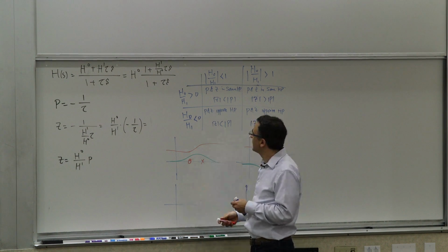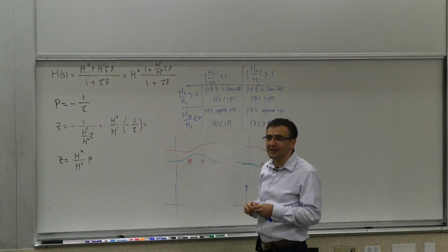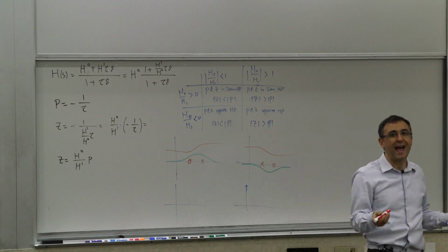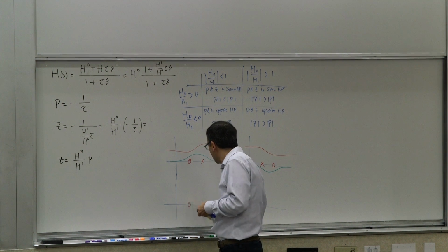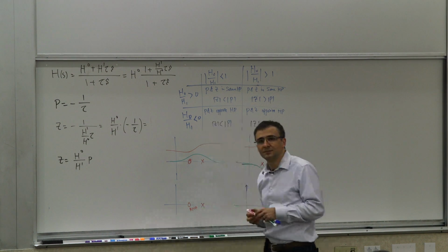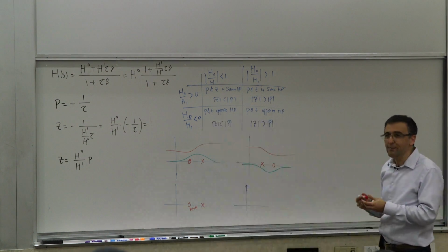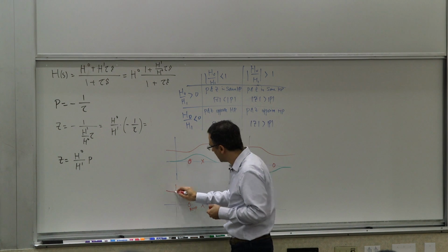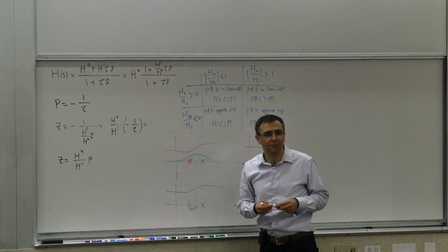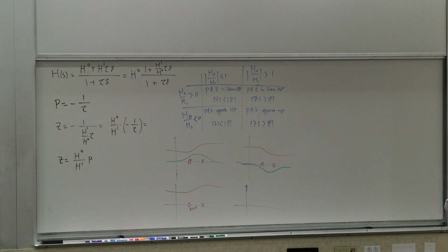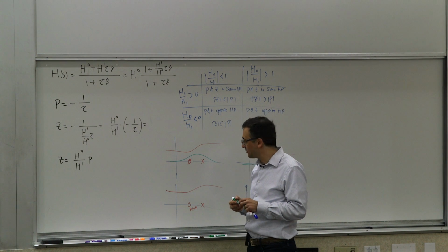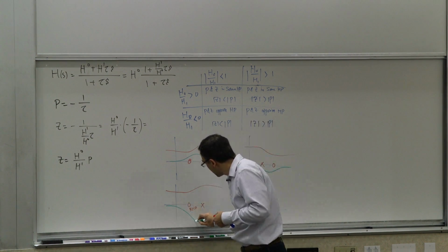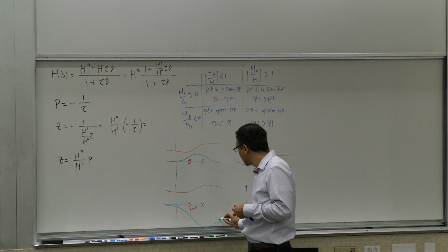Now, how about this case? When they are in the opposite half plane, let's say you have a left half plane pole and a right half plane zero, and it's happening before. So this is the same as that, except for the fact that this is a right half plane zero. So the amplitude response will remain the same, because the left half and right half plane responses look the same. But the phase response is now going to be different, because the right half plane zero has a phase response that looks like a pole. So your phase starts dropping and then drops further to negative 180.